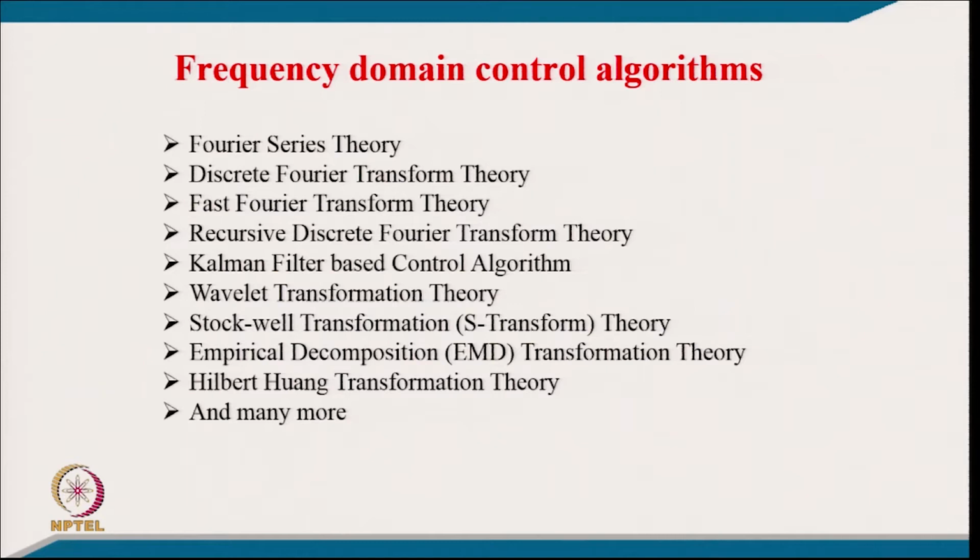Of course, most of these frequency domain control algorithms are normally used in instruments like the power analyzer, which we have shown, which are responsible for getting the total harmonic distortion as well as the different harmonics, reactive power, and active power calculations. The instruments used are called power analyzer, power network analyzer, or power recorder.